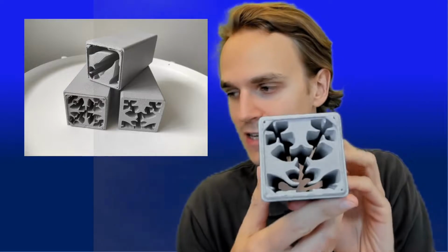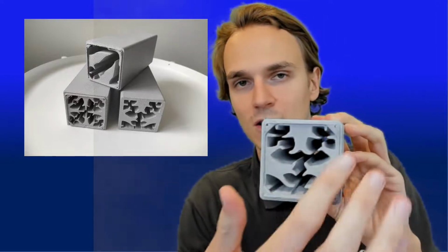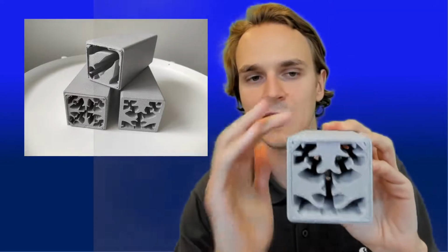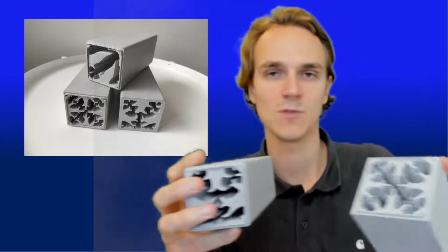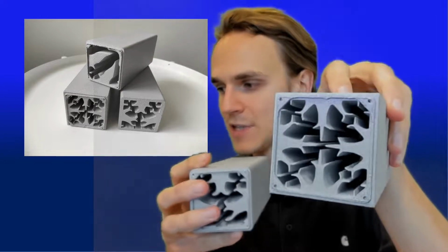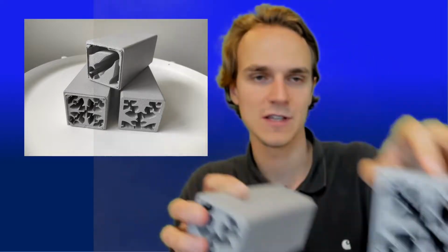Here's the 4th one. And what's interesting is that, of course, ColdStream only generated structures right here and on the sides because the case setup dictated it. So we had heat sources on 3 sides, while this one ended up being a symmetrical design because we had heat sources on all 4 sides of it. And so that really shows how generative design adapts to the needs that you have.